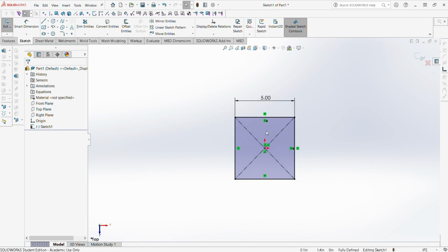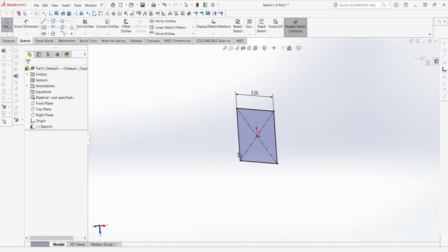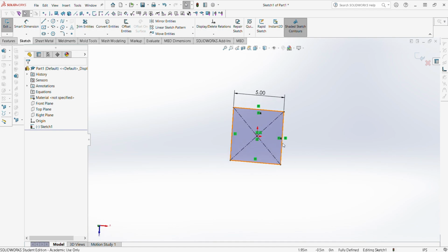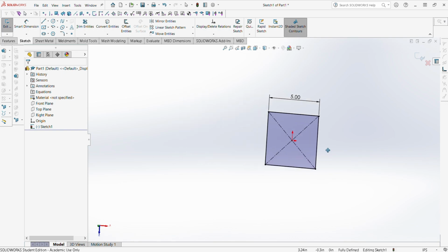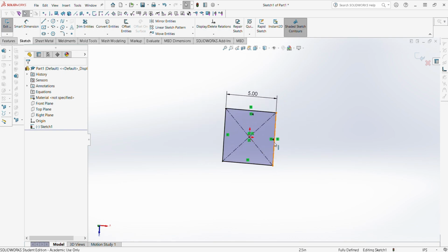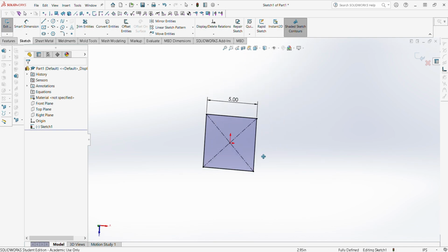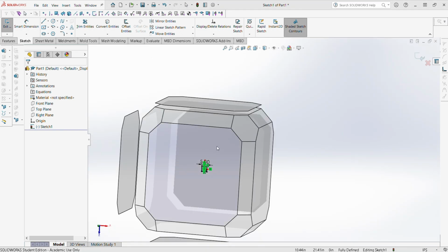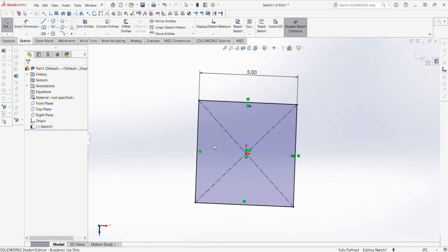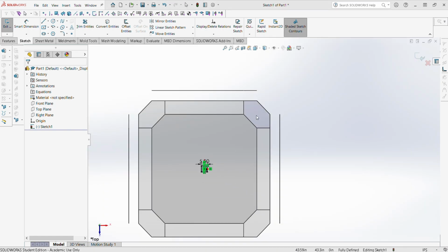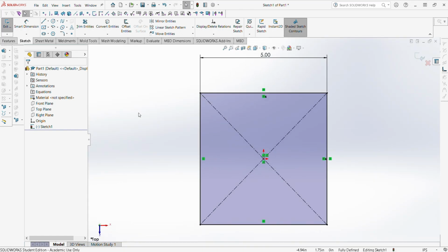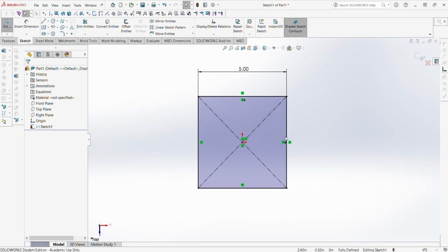But the main thing you need to learn how to do in this software is scroll up and down for zooming in and out, so that's how you move around. And then if I want to rotate this, I click my mouse wheel and just pull and drag. And if you want to move it on the same plane, as you're looking at it, you hold Control, press the mouse wheel, and you can move it around without it rotating. And then we're going to go back to spacebar, and then I can say, hey, I want to look at this thing straight on, or I want to look at what's called isometric. So it's going to show me in the isometric view. These are handy when you're trying to move things around and you want to be speedy with it.